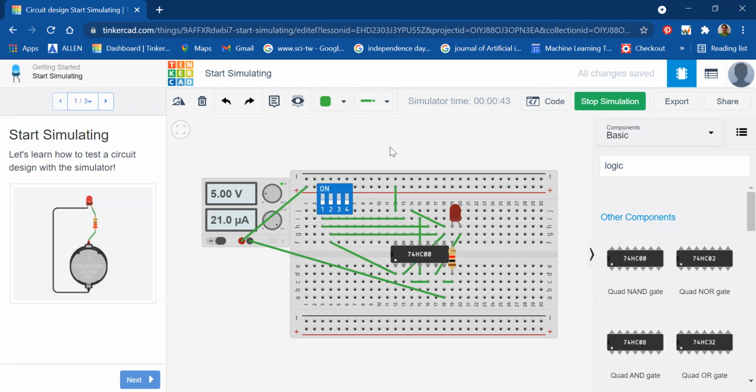So that's all for now. But when you are making the connections, just be very careful, because you have to remember that this first pin is VCC. What I did was I actually counted 1, 2, and this is my third one. That's why the mistake happened. So this is how you prove your XOR gate and design it.